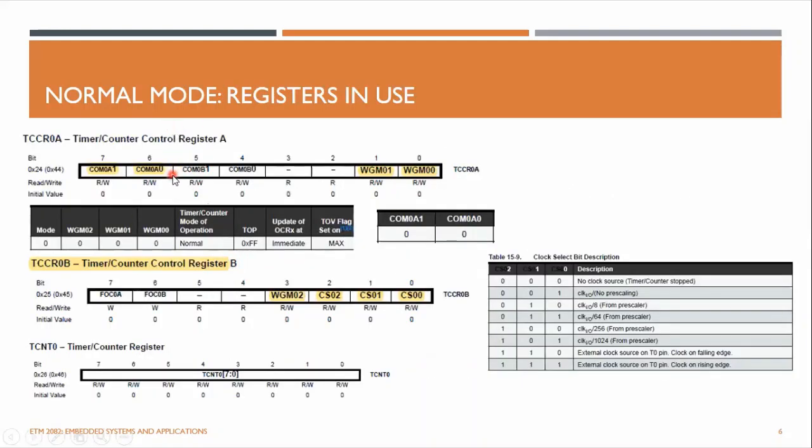And there are some registers in the microcontroller. If you search, these are the registers that we have to use for the timers. The first one is TCCR0A, timer counter control register A. If you search in the data sheet of the ATmega328P, which I have uploaded to the LMS for you to download, it will go to the timers and counters page. So you can locate this register. It has 8 bits, and different bits have different configurations.